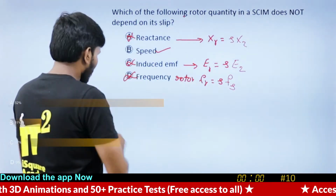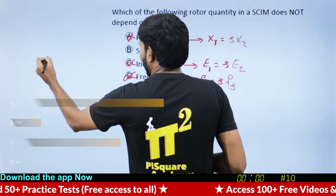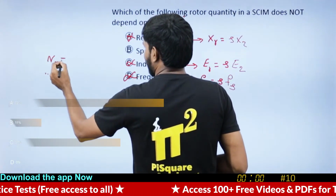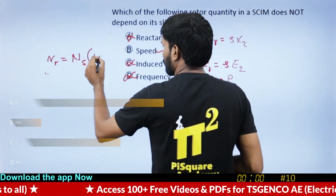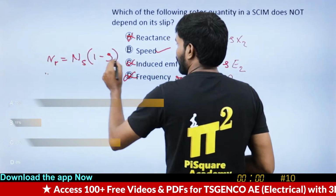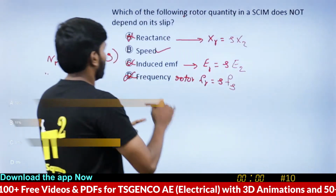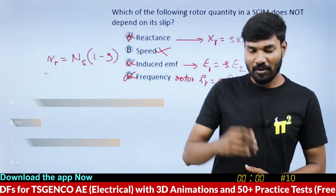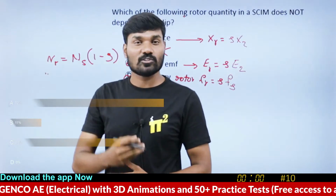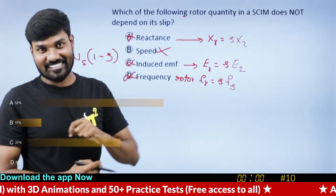Now you may say, sir, this is also not a right answer then, because you know NR is equal to NS into 1 minus S. This is the formula you know. So if slip changes, NR changes. So this is also not a right answer, apparently it seems like that. But Sampath has given a clarity also. Slip depends on speed, but not vice versa.